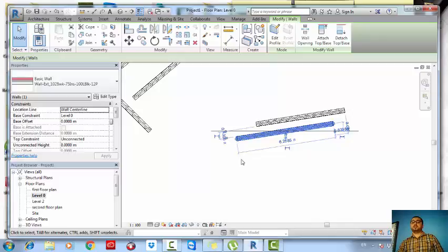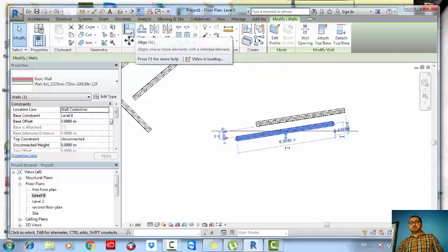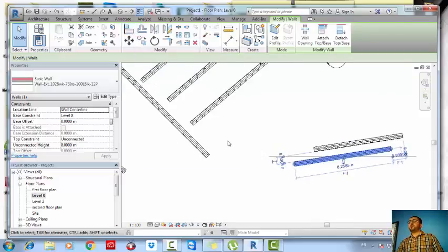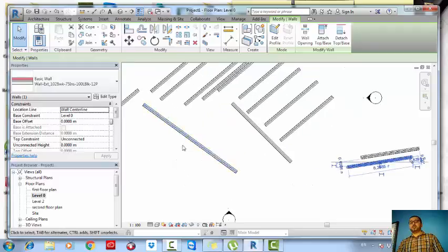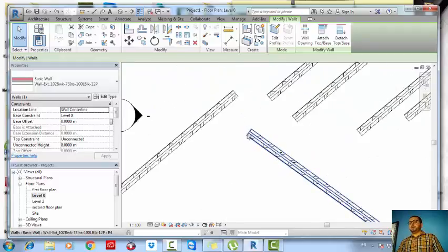Fine. So you can either keep your center point in the center of the selection or change it as you need. The third tool or the fourth tool, let's go for align and offset. It's also a little bit similar to AutoCAD. If you are aligning a wall, for example, I want this wall from this edge to be aligned to this wall on this edge. Fine. So it will remain in its place and it will change its orientation. Fine. Go to align or AL.